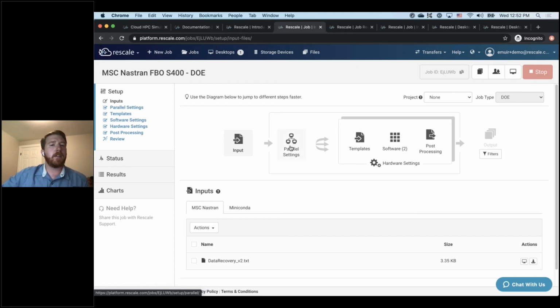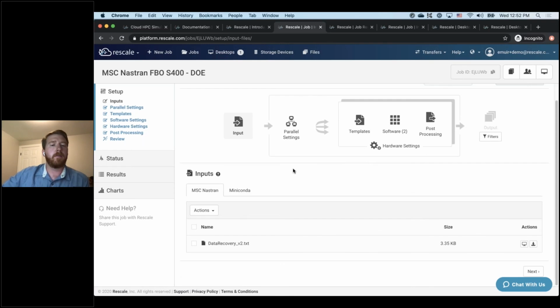And what this ultimately lets you do is to specify all the different jobs that you want to run, defined by variable parameters, and then allows you to insert the values of those variables into a template input file so that you can run this over several tens or hundreds of inputs without having to manually create those input files yourself.